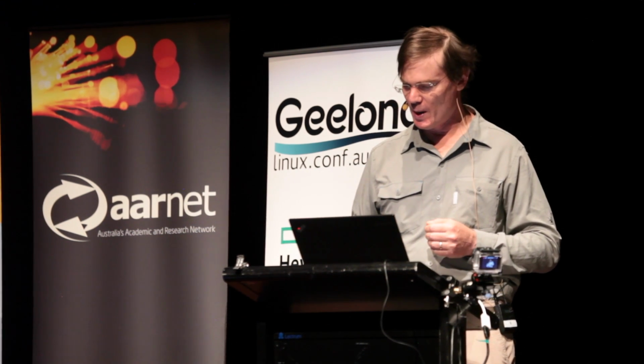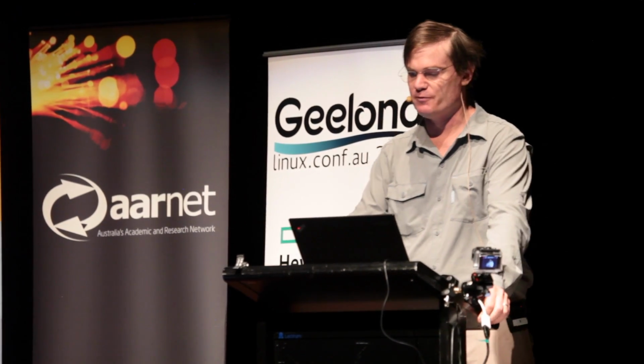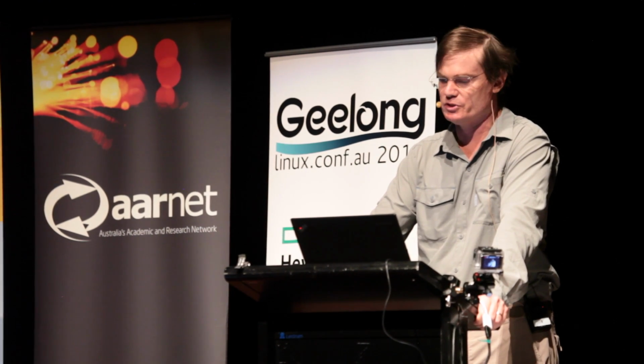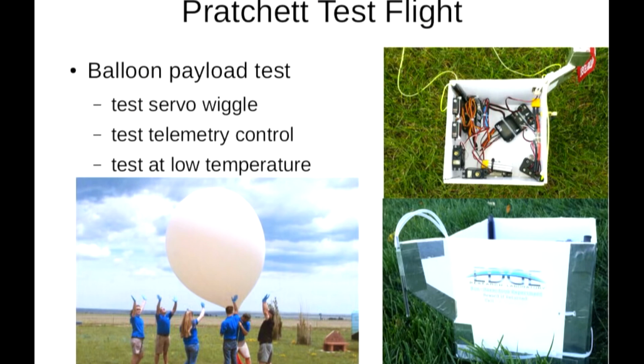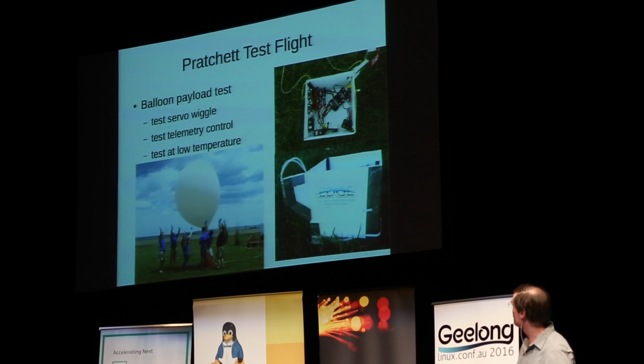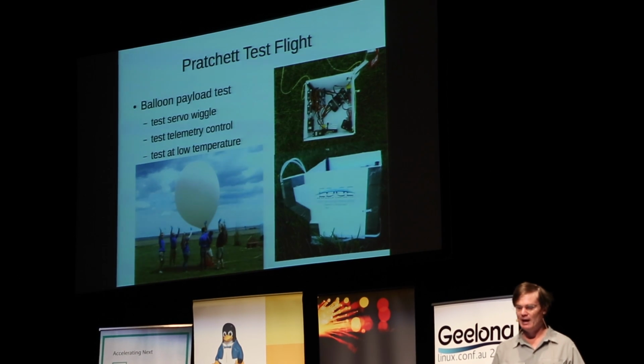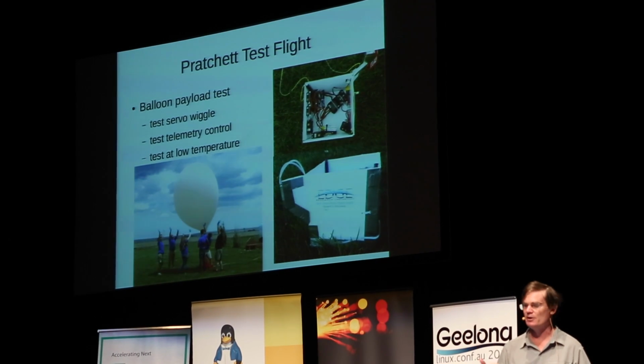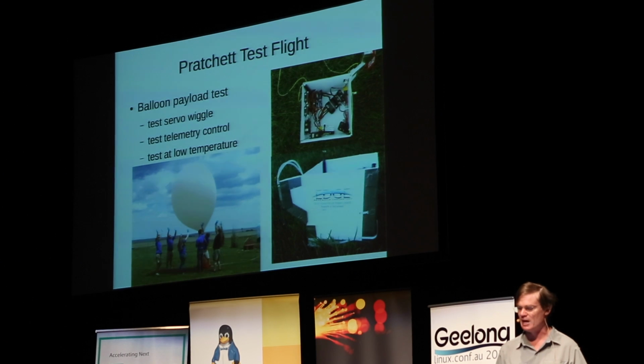Anyway, we need to do lots of test flights, but we can't test flight the actual plane. This is a one use plane, so we just test flight all the avionics on board, the electronics, the servos and the autopilot. We worked with the EDGE team in the US that works on high-altitude ballooning, a fantastic group of people, and they did a test flight for us on their balloon where we were able to test at least that the code worked, the autopilot could survive the temperatures, that the sensor data looked good, that the servos didn't freeze up, that type of thing.